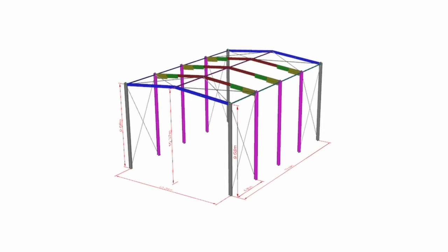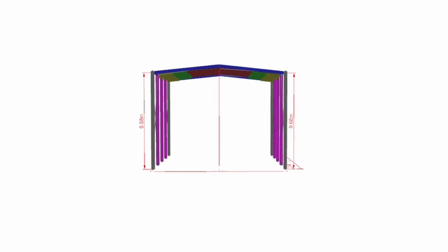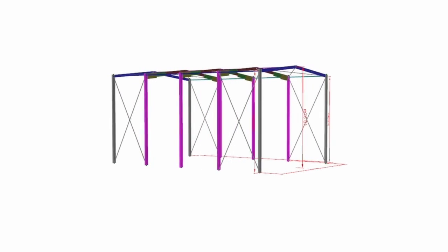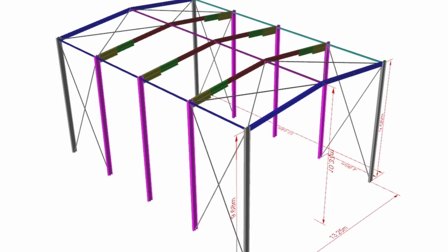Here you can see the basis of our Space Gass model. The dimensions were determined based on those given for our Revit model. Additionally, our columns, rafters, purlins, and girts were based on those chosen for our Revit model. In some cases, Space Gass did not offer the exact size needed, in which case we decided to size up to the next closest available option.